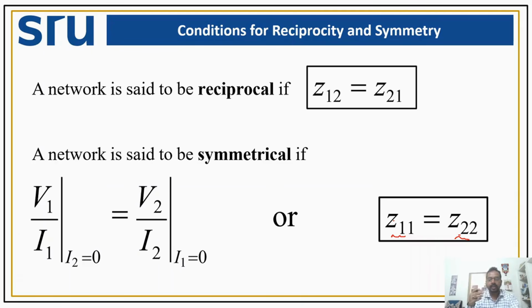On the other hand, consider an amplifier circuit. Your amplifier circuit is not symmetrical because it tries to send the signal in one direction. So if you look at the input terminals, you see a certain impedance designed for signal reception. But if you look from the output terminal, the impedance is usually very different because it is designed to deliver power to the load. Therefore, most active circuits are asymmetrical. Symmetry is mostly a feature of passive and balanced network structures. From a design perspective, symmetrical networks are easy to analyze and often provide predictable performance.